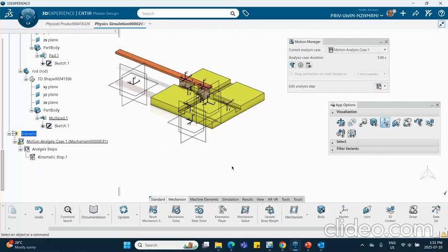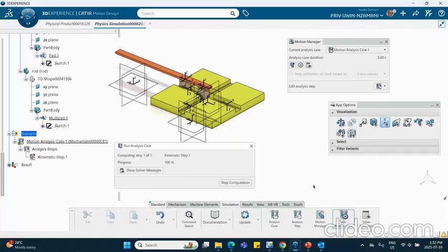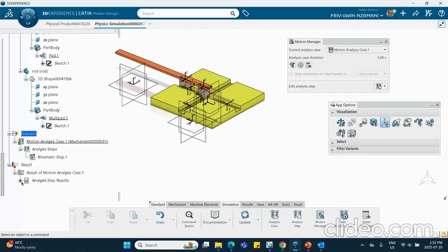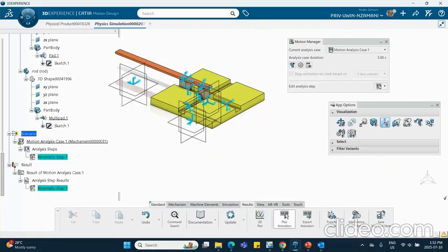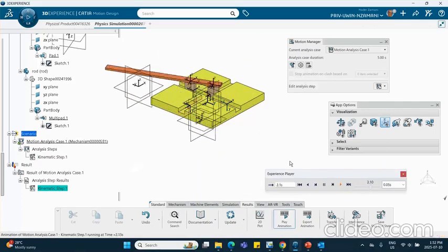Exit. Let's go and simulate simulation. Run it. Wait until it finishes. Close it. Select the result, the last file. You want to do animation, select this. Go to result. Here's the animation. And play it for 5 seconds. Duration of the simulation. There we are.